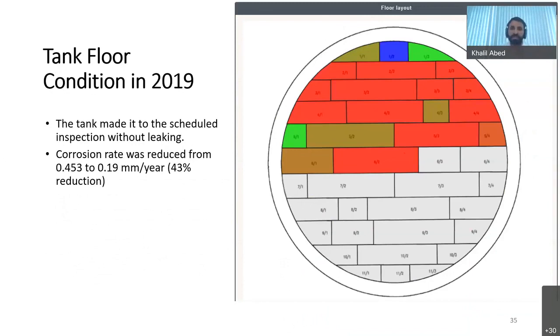After injection of the tank with vapor phase corrosion inhibitor powder, the tank was boxed up in 2013, and it was opened in 2019. Since the main objective of the tank owner was to avoid any tank leak with minimal repair for the next 6 years, this objective was achieved, and the decision to replace the entire tank floor in 2019 was already taken in 2013. They just wanted to keep the tank with minimal repairs until it reached 2019.